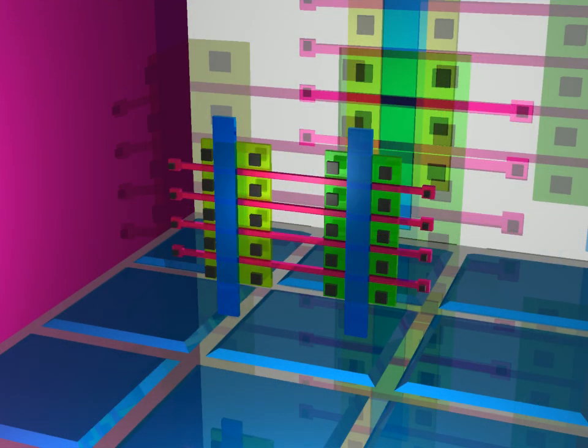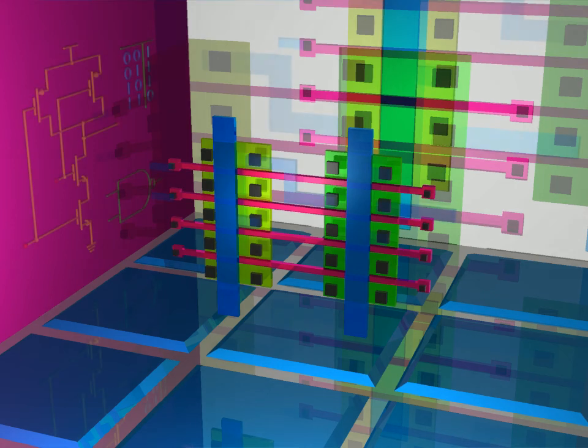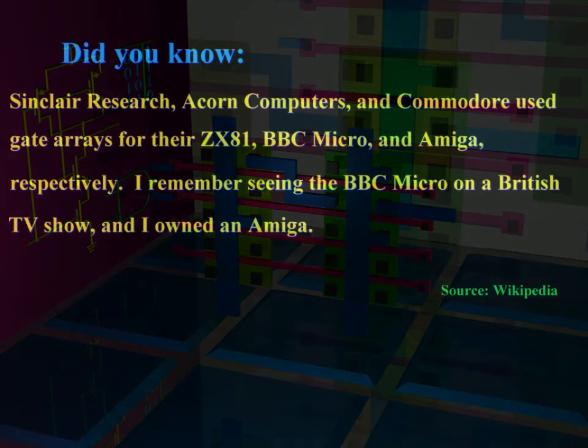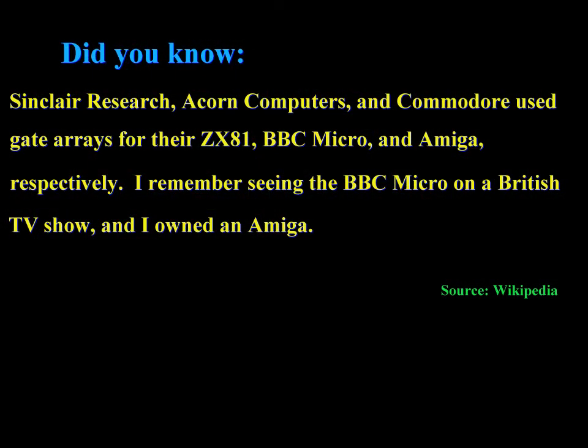Blank gate arrays are formed on the silicon wafer with the polysilicon, diffusion, cuts, and basic metal strips, which are not contacting anything, all formed in the first stages of the process. Then all a manufacturer has to do is make the metal connections needed to form the desired circuit. Kind of like writing to a blank CDR, but not as easy though. Each gate array chip may have several thousands of transistors, which is many more blocks than what I modeled.